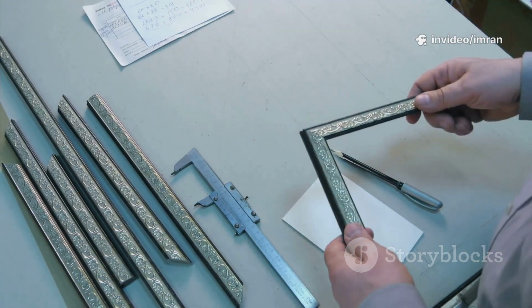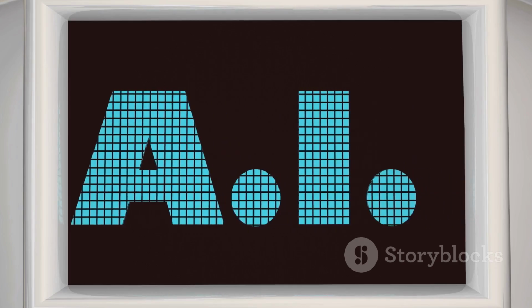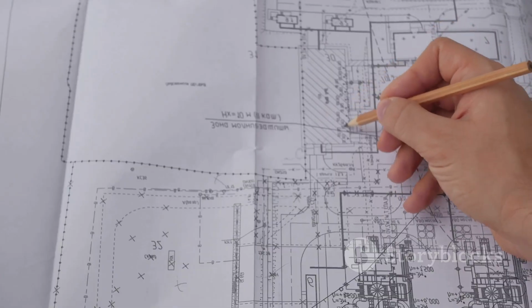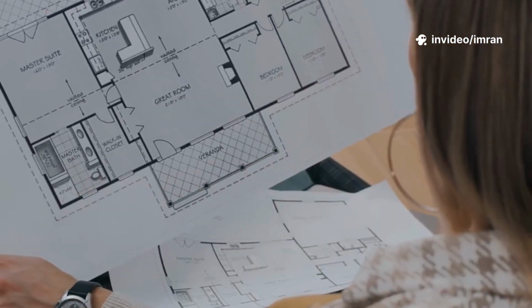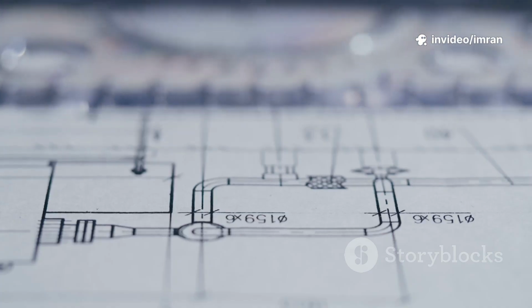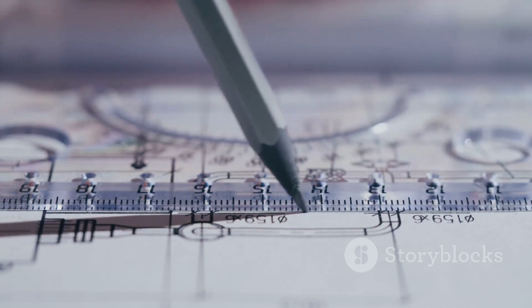The final step is to add dimensions to communicate the key sizes of our layout. Change your current layer to A dims. On the ribbon, go to the Annotate tab and use the Dimension tool. Use this tool to add the overall length and width of the room. You have successfully created a complete, organized, and dimensioned floor plan.